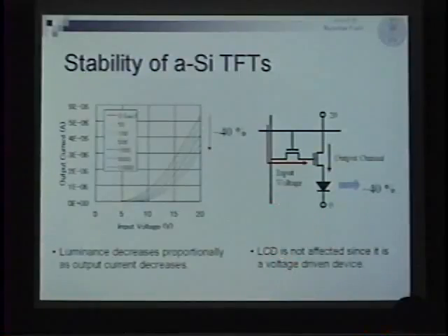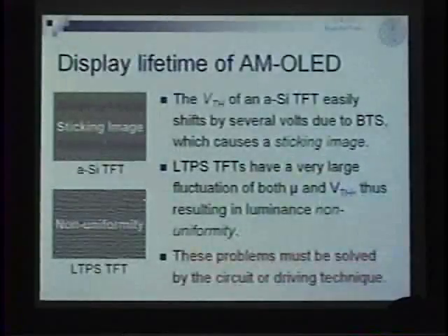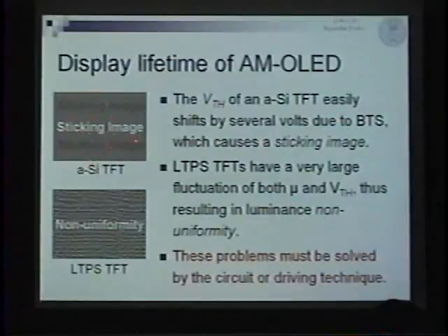By the way, the LCD is not affected by this because it is a voltage-driven device. So this kind of instability doesn't matter for LCDs. Next, please. That kind of instability appears on the display like this as a sticking image.